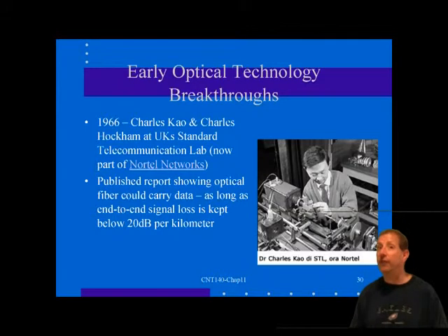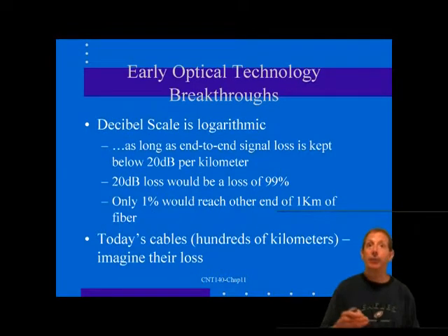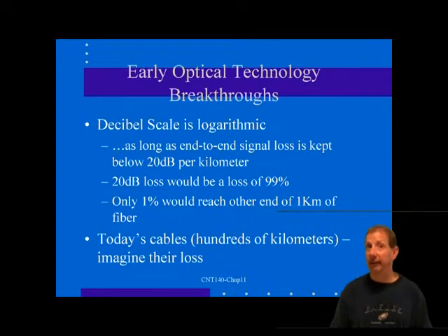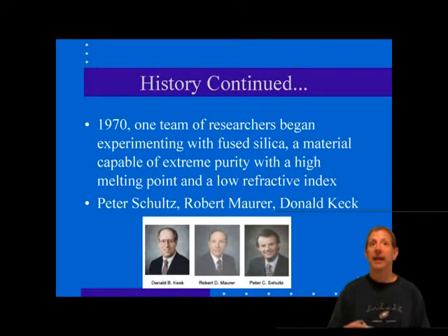Let's take a look at the different fiber types. Optical fiber is available in both glass and plastic compositions. Glass is the most prevalent in land uses because of its inherently greater bandwidth. Several uses for plastic fiber exist, and this is an area that has had more development over the past several years. However, at this point in time, the higher bandwidth and longer distance requirements of modern networking still demand the use of silica-based fiber in most applications.